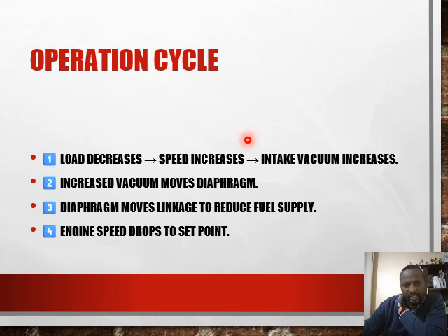Once the throttle valve closes, it means that the air is now struggling to pass through. As the pistons are moving up and down, sucking air into the engine, the air is struggling to pass through, therefore we have a higher depression. This depression then acts on the pump rack and retracts the pump rack to give us the minimum fuel for idle.